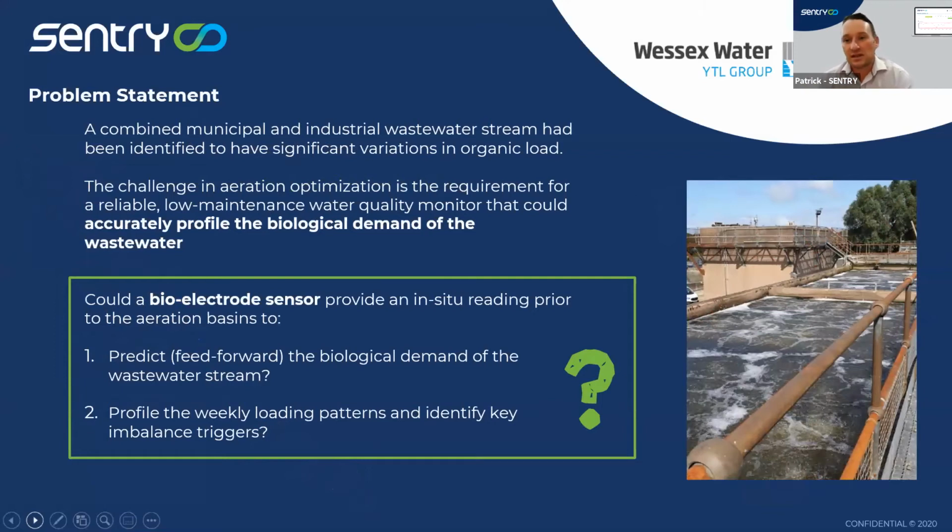It was a wastewater treatment plant that had a lot of traditional municipal wastewater coming in, but also had one key industrial discharger, a food production or food processing type facility. They were discharging big slugs of BOD and COD, but not always the same quality, not always the same volume, maybe not even always the same time of year. So it was very difficult for Ivor to understand and optimize his own process downstream of that.